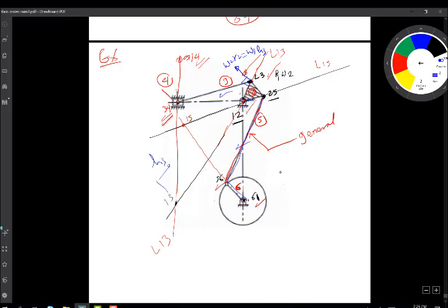So really this linkage connects a 4-body chain and a slider crank linkage. And we have shown before, possibly I would have done a 4-body chain example for you earlier, how to find the points. So you can keep solving this problem to find omega 5 if you wanted. I can find omega 5 at this very moment, simply because I have 1,5 here, and I have 2,5, and I know omega 2, right?